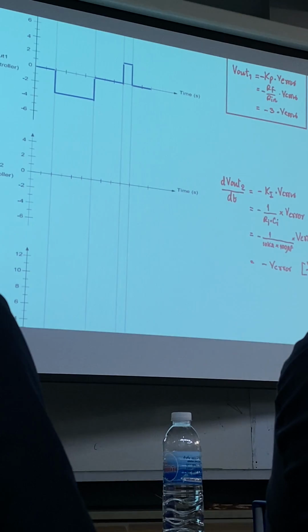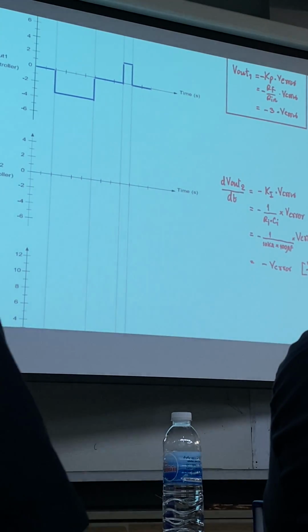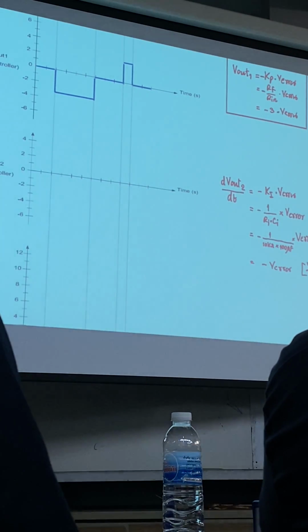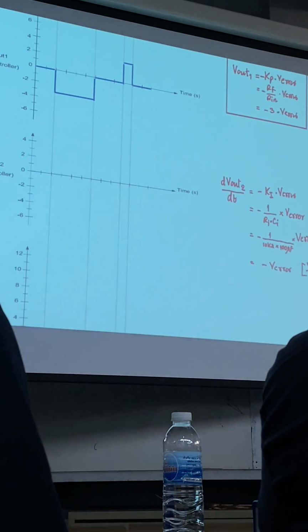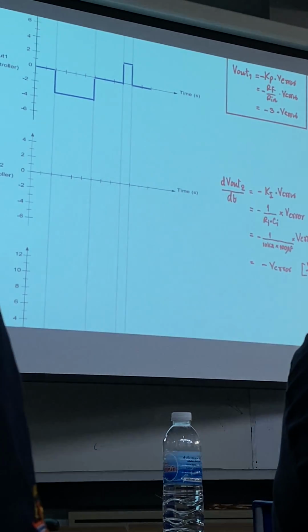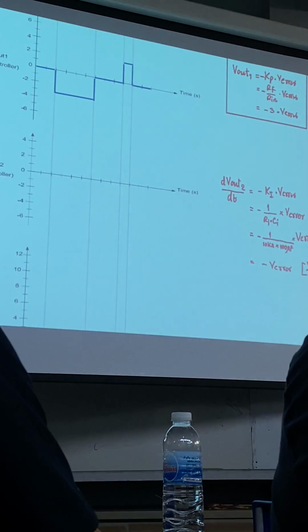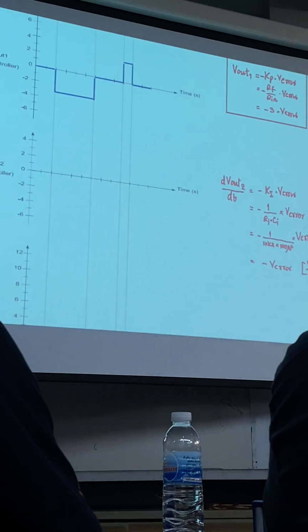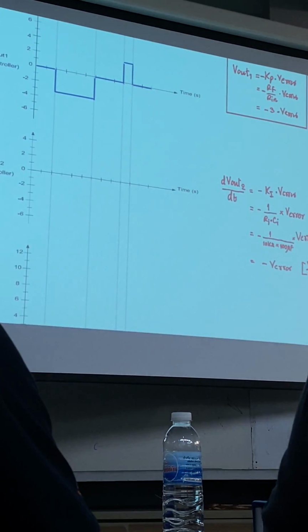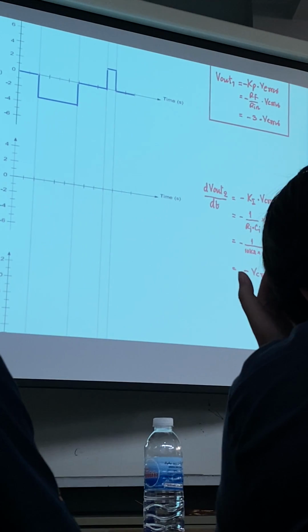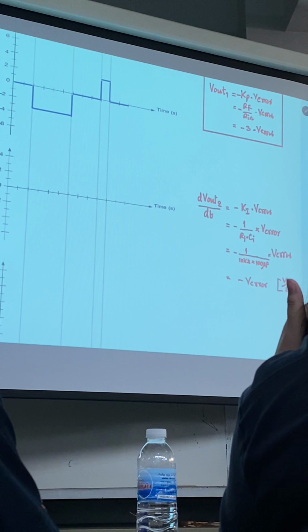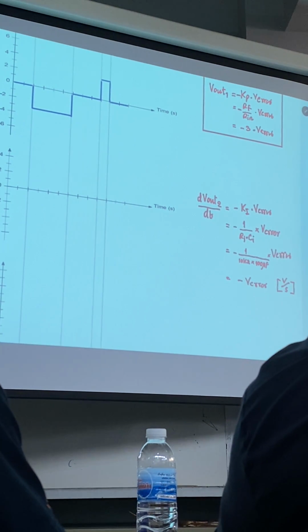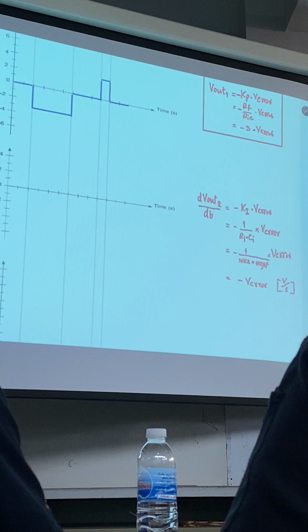Last time I told you that when you make the integrations, you always have V plus V0 at the end of the equations. What is the meaning of V0 at the end of the equations? It means the voltage at the beginning. So I have to define the beginning voltage of the capacitor that we use in the integrator circuit. And now I will define it as 0 volt.